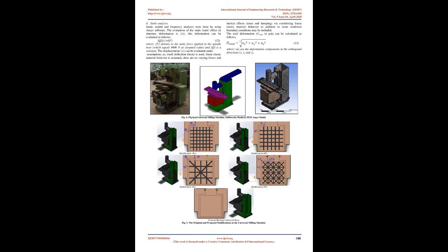The code uses the horizontal and vertical scroll bars. Scroll bar events are used in this code. The designer uses this event to retrieve the cutting parameter after any changes in the scroll bar. As the user changes the scroll bar value, both the cutting force and power are calculated, in integer format, and animated lines on the electronic nomogram are displayed on the computer screen as shown in Figs 1 and 2. The formula for cutting force and power is given in the analysis.